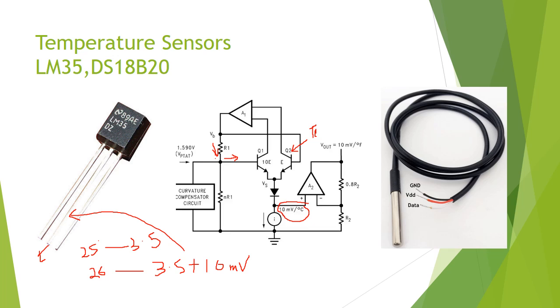That data pin will send the signal to your microcontroller, and the microcontroller will sense it. This is the amount of voltage coming in, and it is analog data. Now you have to do some programming to convert this millivolt to degrees Celsius, so that it makes meaningful sense. So this is how your LM35 works.